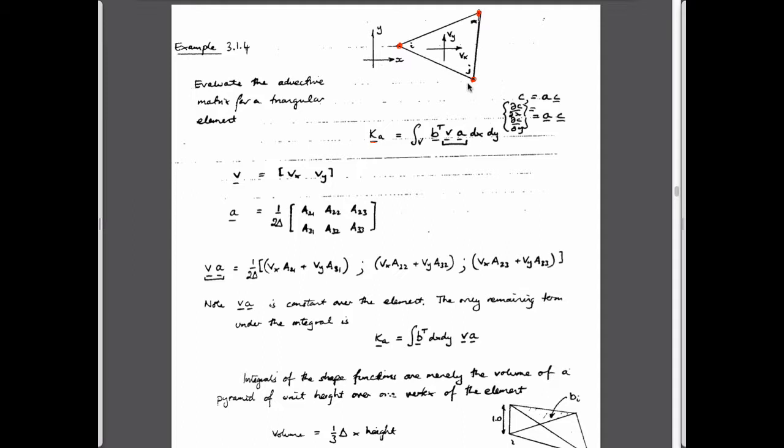Imagine the concentrations or the heads being the elevations of sticks above each of the nodes. The plane that goes through the points of those is the equation of a plane, right? A plane uniquely goes through 3 points. And so if we know what the equation of that plane is, we can use that as our mapping function to be able to map the heads from node to node. So we never explicitly define shape functions. And so we will approach this in a slightly different way.